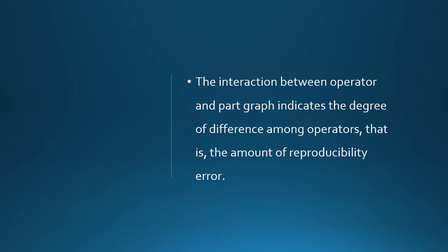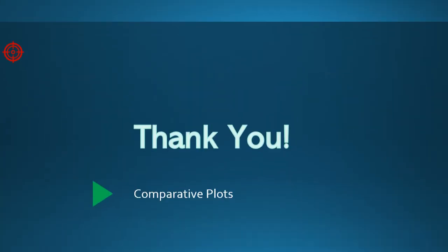So let's review. In this lesson, we used the interaction between operator and part graph to evaluate the degree of difference among operators, that is, the amount of reproducibility error. Next, we'll look at the comparative plots for a different look at variation. And thank you for listening.